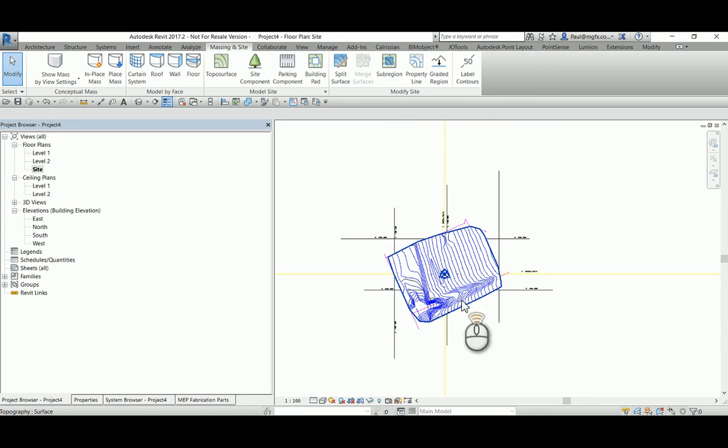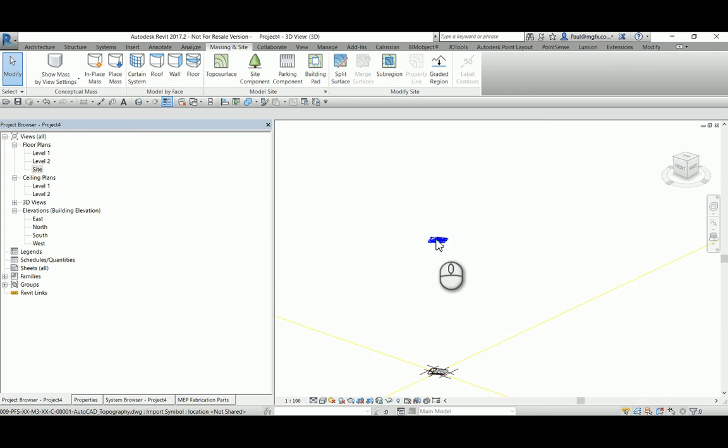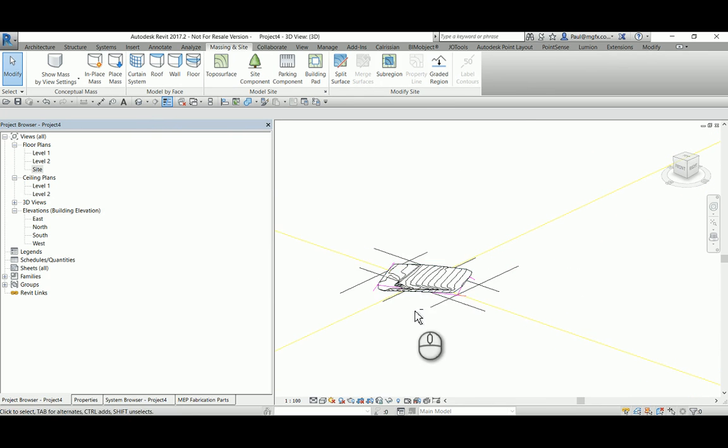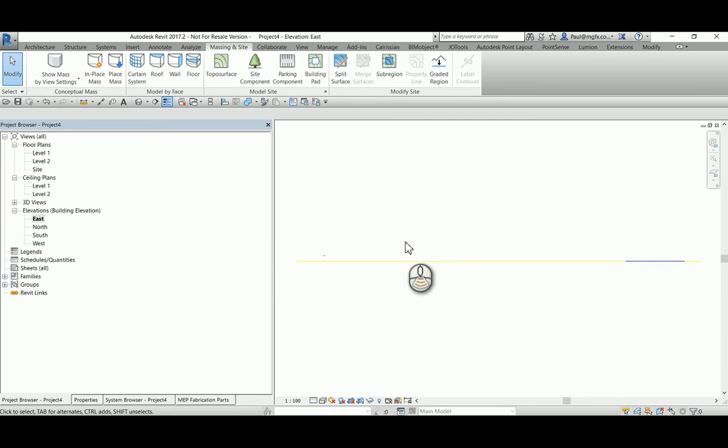And what I can do now is look to see whether the contours and the topo surface that was generated from the points file correspond to one another. That is the check. And you can see this is generated around the 0, 0 at the moment. So we fix that as follows, or not fix, we investigate it as follows.